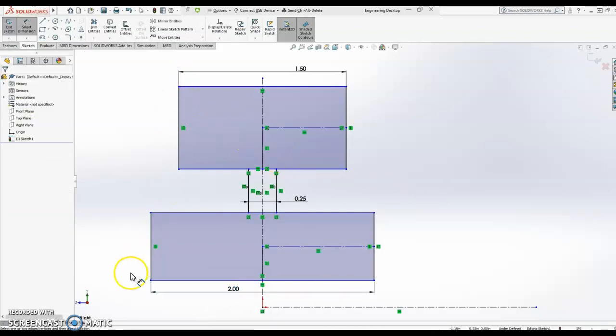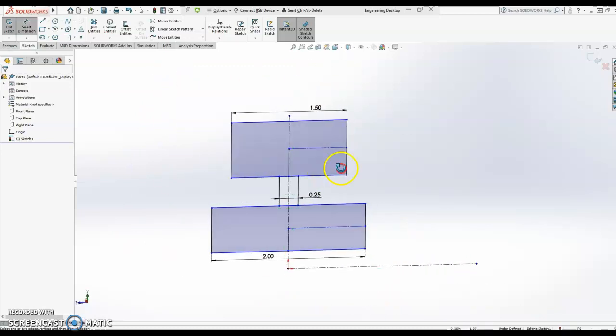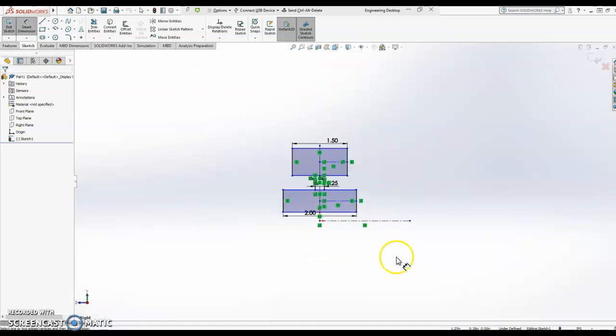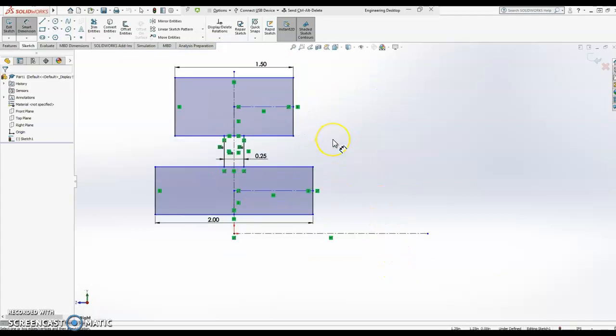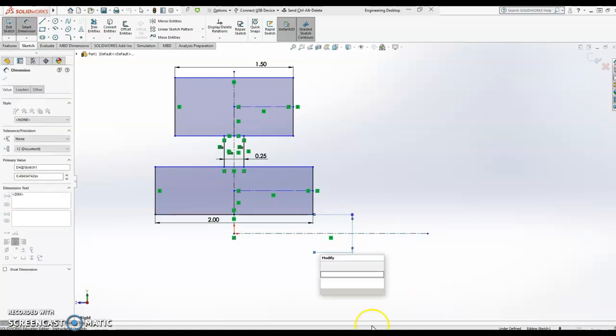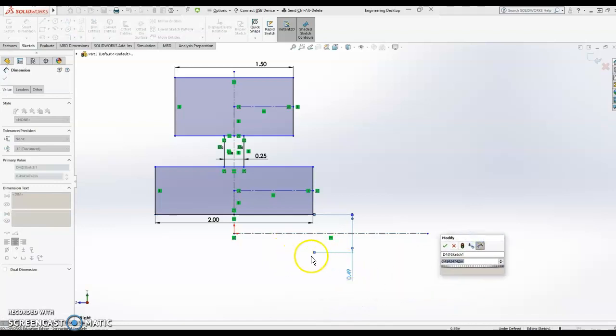You'll notice that all the vertical are black, which is good, but none of the horizontal are. So what we want to do is put in our diametric dimensions because it is going to be a rotational part. Now, I have the center line here, so I can do something kind of neat. If I click on the line I'm dimensioning, click on the center line, now you can see that right there says that it's 1/4 inch, but if I drag it to the other side, notice that now it gives me a dimension to nothing here, but it says 0.49 inches.